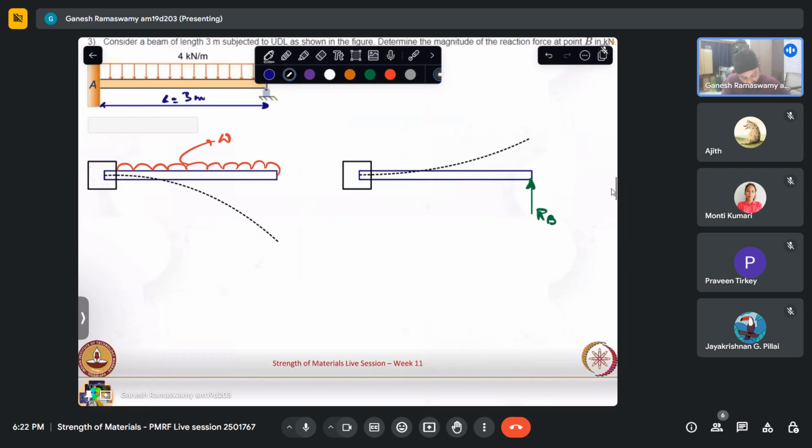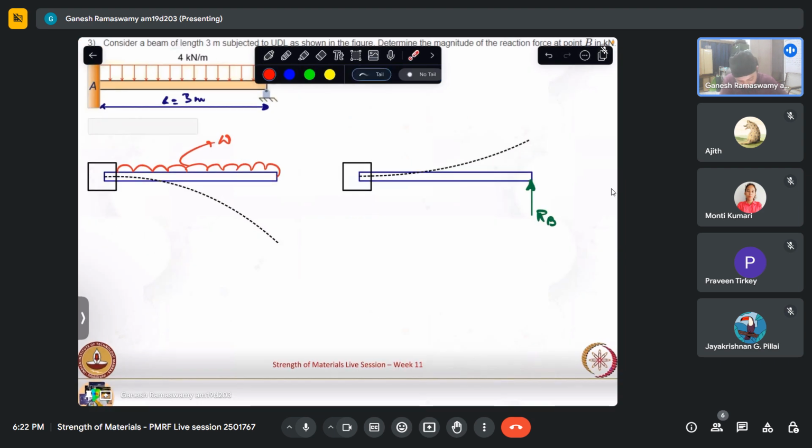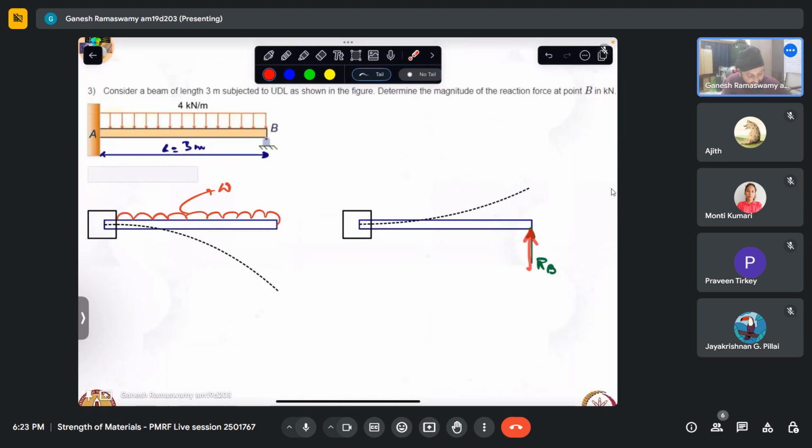So we can see that once we have a cantilever and we load it with W, it goes down by a certain amount because of the deflection of the free end. Whereas if we were to prop it and consider that reaction alone, it will be deflecting somewhat in this manner. Now, if we were to superimpose these two together, what is the end result?